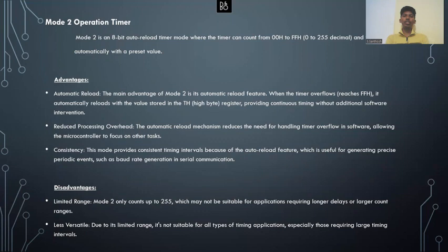So we saw that while using looping statements also, the microcontroller may take a long time. Just like that, even while using mode 1 operation, it might take a slightly longer time than mode 2 operation. So to reduce the time taken by the processor, we use mode 2 operation and reduce its tasks to go through the looping statements, or to auto reload the values given to it.